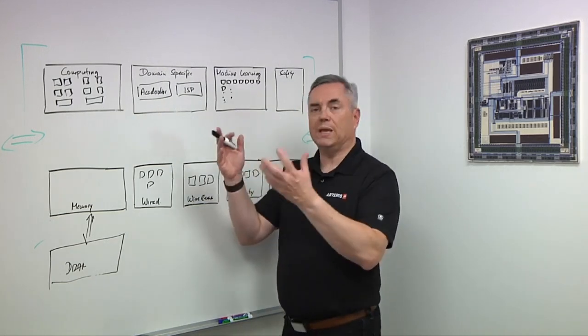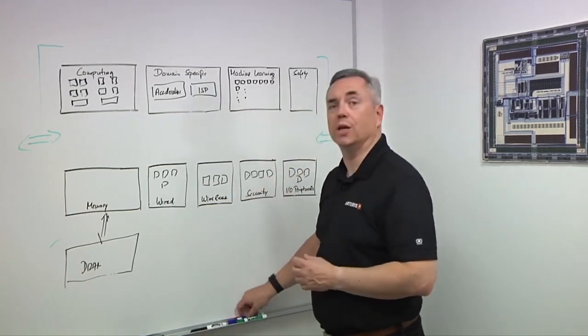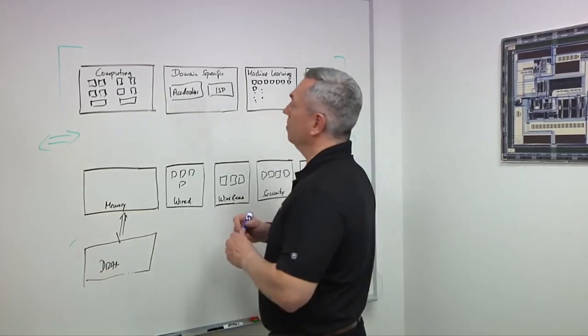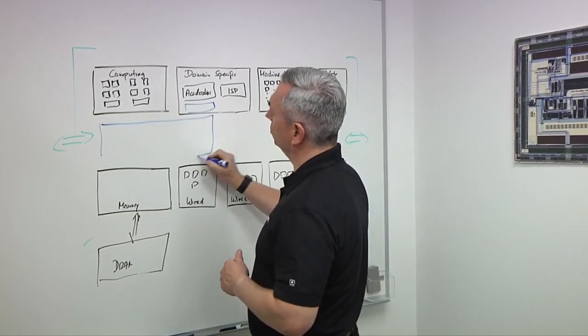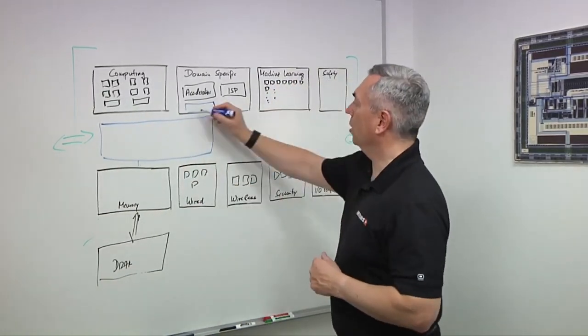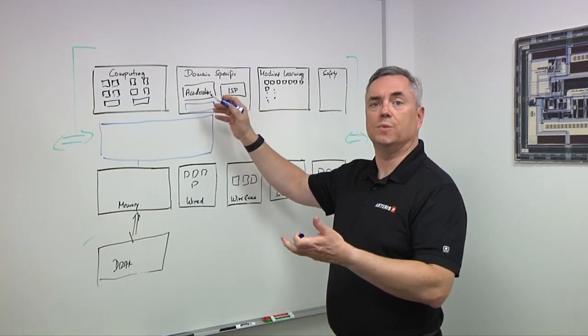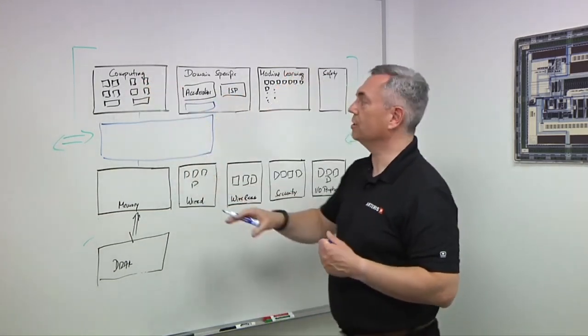Right, so the two big items to consider first is who is actually sharing memories, right? So this guy here may share with the compute subsystem this memory here. So you have cache coherency to be considered with these caches coming from the compute subsystem.